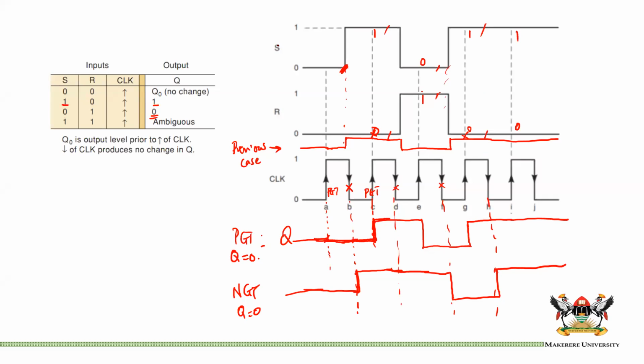So if the clock is constant, there would be no change in output. Patricia, that is true. And I believe that by saying if the clock is constant, you mean that there are no transitions. So if you have one pulse forever, yeah, no output would happen, but that's no longer a clock. A clock should be like a square wave or a rectangular wave.